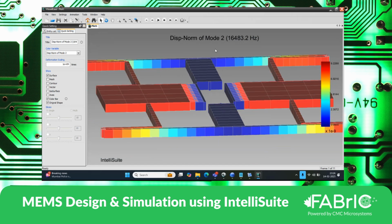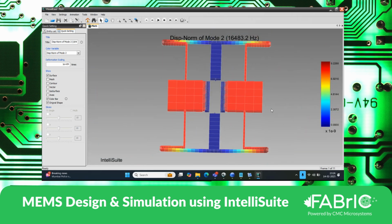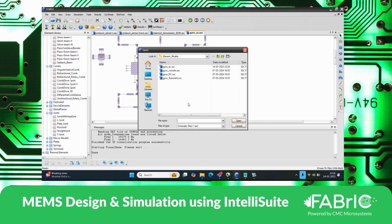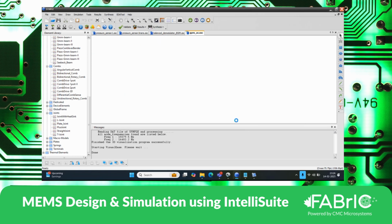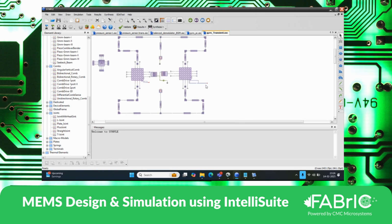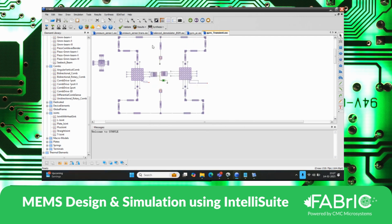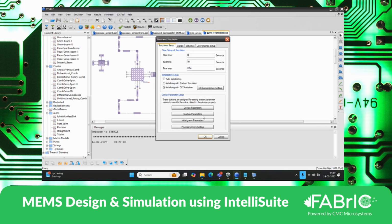Okay, so this is how we can get element-based modeling simulation output also. And this was purely a frequency-based analysis. I can perform a transient analysis. In this, I give the input signal as pulses. So here I give a voltage AC source, and this frequency. And then we perform a transient-based simulation.